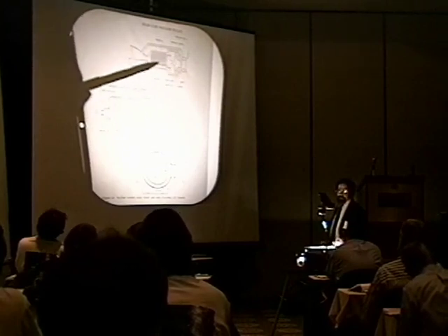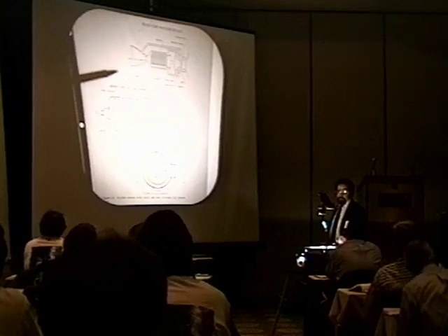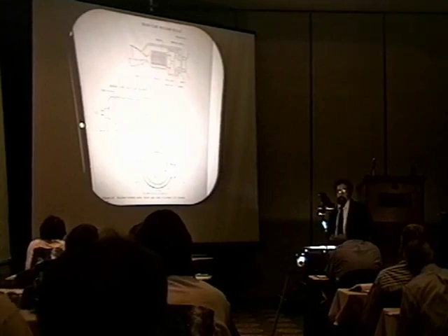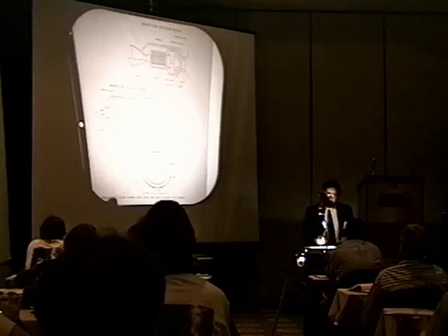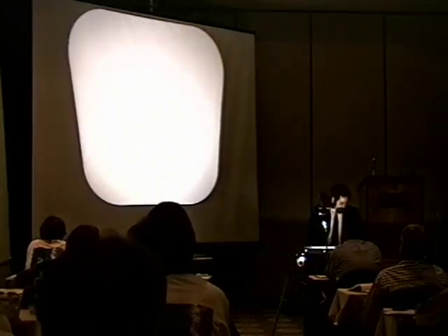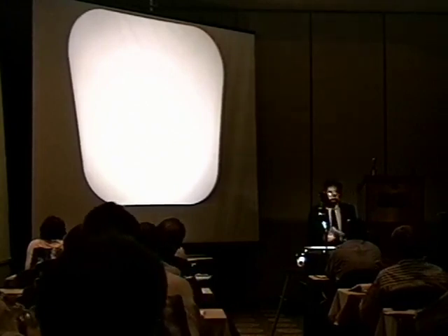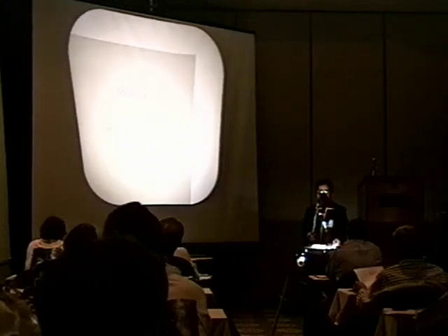Hydrogen was passed through this solid core nuclear reactor to give an exhaust jet which produced up to 200,000 pounds thrust, tested on Earth at a very high velocity, which meant it was a very efficient rocket. And later on, there were other concepts that I'll return to, suggesting ways that we might have cold fusion replace that nuclear reactor in the solid core and even in the liquid core.